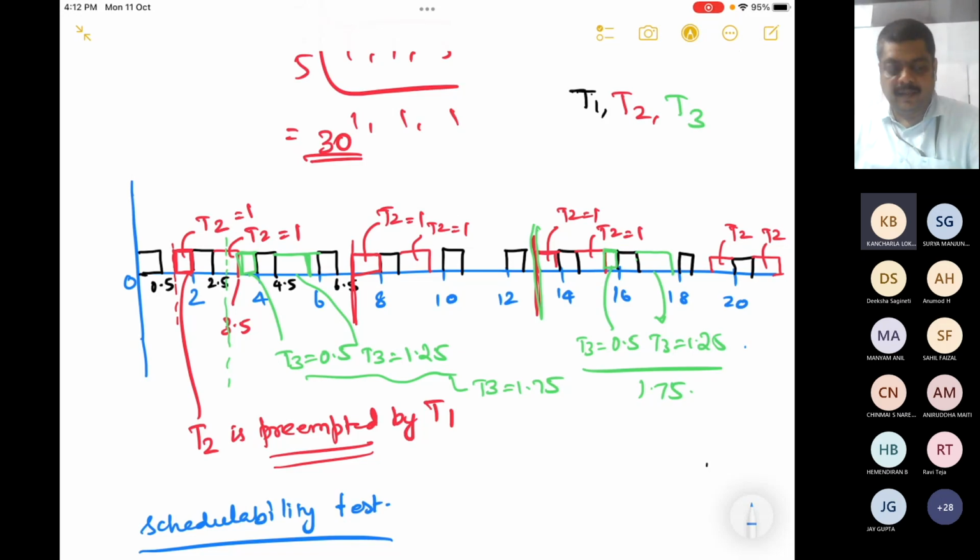If you take the example of a Tesla self-driving car, let's say applying the brake when an obstacle comes in front of the car, and that is controlled by one CPU, and the same CPU controls some other task as well. The high priority task is to stop when there is an obstacle in front. Suppose at that time a low priority task is not giving up the CPU and the high priority task is waiting. In that case, no brake will be applied and the car will hit the obstacle. That should not happen in an embedded system. That's why in 100% of embedded systems, the task set by default will be preemptive.